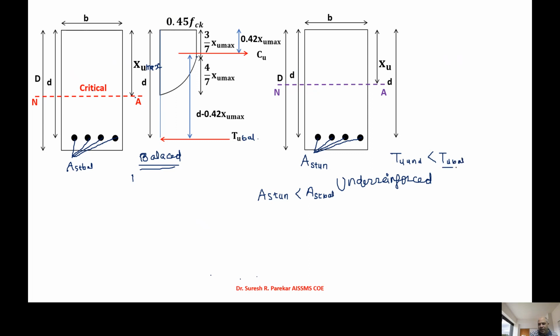As this is less than TU balanced, the compressive force is also reduced because we know CU under reinforced equals TU under reinforced.